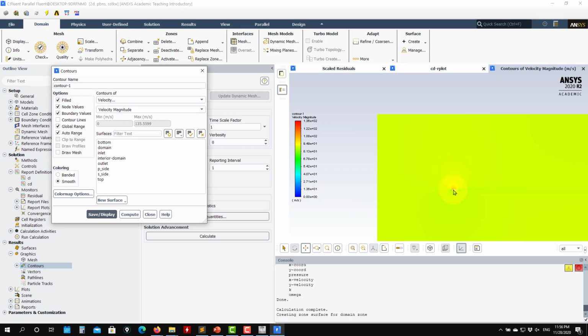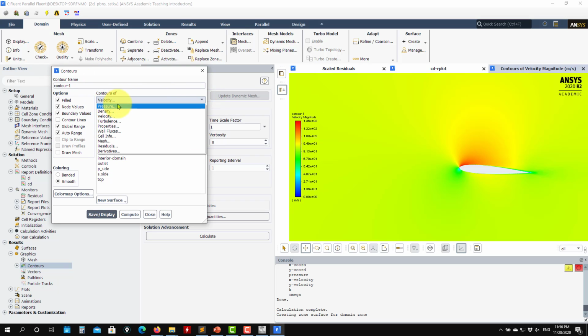Okay, and in this wall here, remember that this is a wall, but we disabled the boundary layer. So see that this gives you much more information than a potential solver. Okay, and funny, it can be faster than potential solvers also, than panel methods using a lot of panels. So here you can explore the quantities, but for our purposes, we're just interested in pressure and velocity.